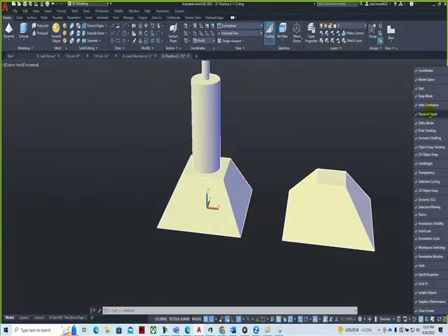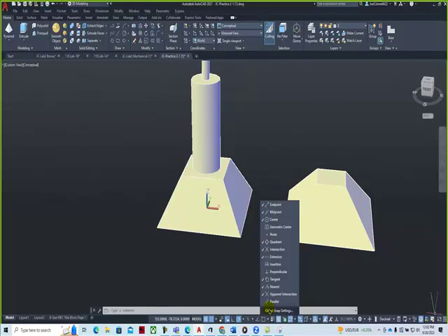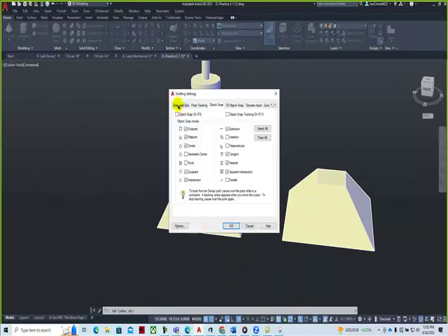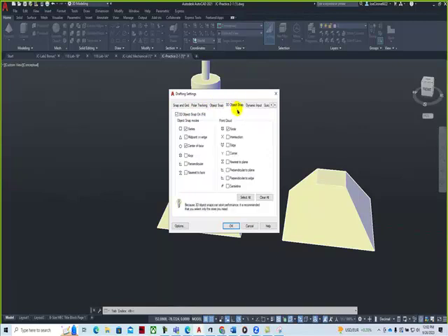And so dynamic input, and I'm actually talking about dynamic UCS, dynamic meaning automatic, so dynamic automatic or dynamic input is this one right here. And if you use dynamic input with object snap, when we look at our O snaps, we want to have our 3D O snap on or enabled.